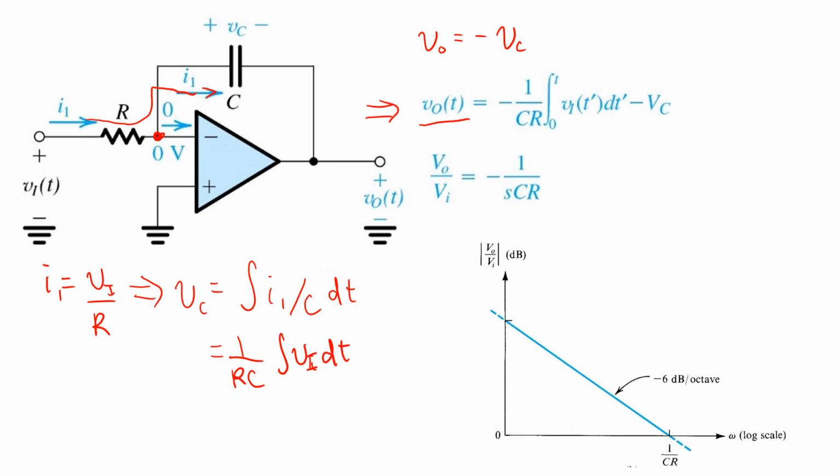And that's the expression shown here. Now, you'll notice that here we have placed the lower limit of integration somewhat arbitrarily at time t equals 0. And so the assumption is that at time t equals 0, the capacitor C had an initial voltage across it equal to VC.